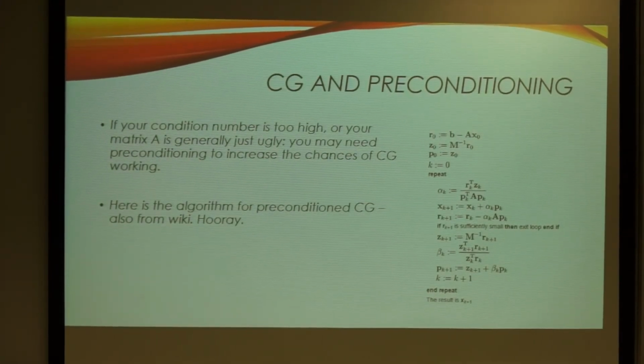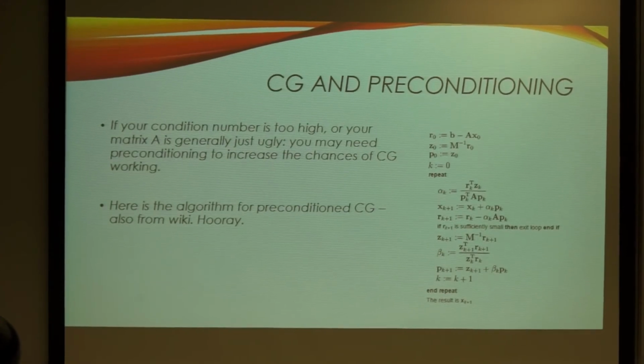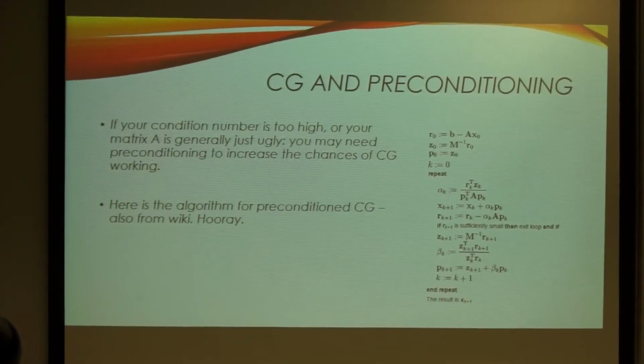If your condition number is high, and you might discover this today, for example, if your CFL number is very large, you're going to get a high condition number. If you have a high condition number, you may need to use preconditioning. Guess what? Today you don't need to.